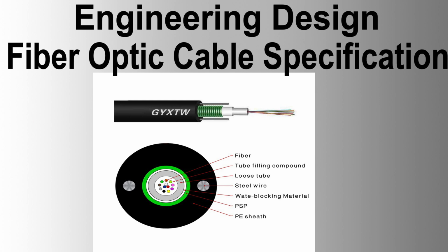Color coding. Each buffer tube is distinguishable by color coding as per EIA TIA 598A. Optical fibers. Specifications must meet ITU-T recommendation G.655 and detailed specifications provided. Each cable must have traceability of the optical fiber back to the original fiber ID number and test parameters. Core construction. Design. The central fiber optic unit consists of a core of loose buffer tubes around a 2.5 mm, subject to vendor design, GRP anti-buckling and strength member.